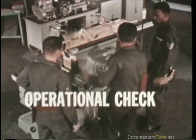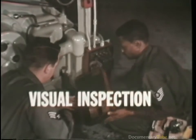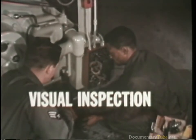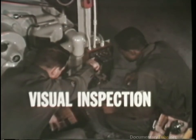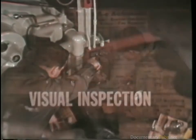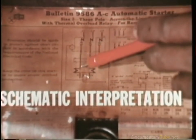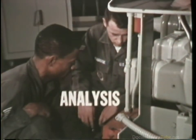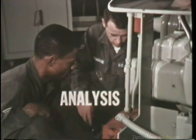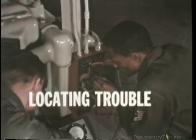Make an operational check of the circuit. Conduct a thorough visual inspection. Study the schematic diagram if it is available. Analyze the information that has been obtained. Locate the actual position of the trouble.